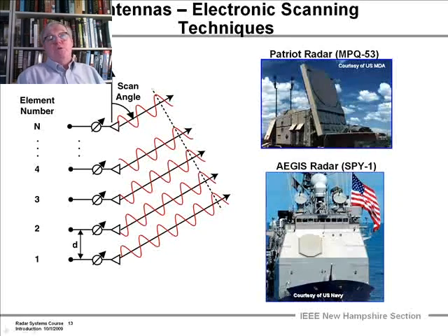And here are two radar systems that use phase shifters. They're a big flat plate with thousands of phase shifting elements in them, lots of transmit-receive modules. Well, these particular ones don't have transmit-receive modules on them. The energy is transmitted out. This is a lens array, and the phase shifters are located in this face.